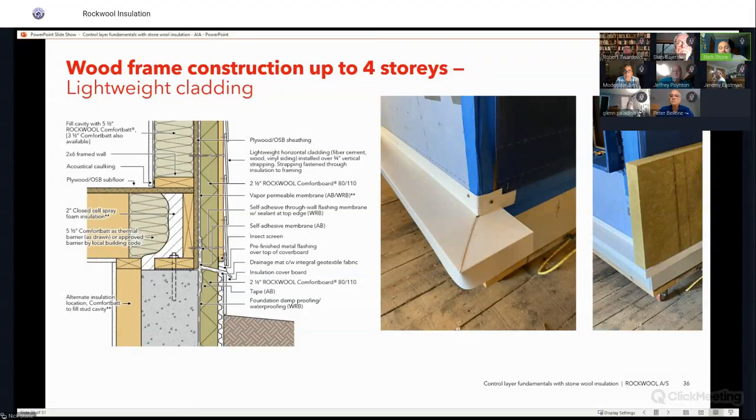But we do spend a lot of time, my team in particular, going out to job sites, showing them how to do some installs. Every installation has a quirk, so we talk about some of the quirks of ours and make sure they're comfortable with that install. When they come to a box, they know that we have to cut the box out, but behind the box there's a void, so we have to fill that void in, so that the continuity is in there. We go through a lot of those little quirky areas. That's something we work on every day. Okay, thank you.